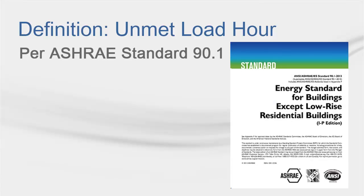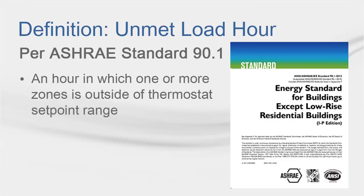Per ASHRAE 90.1, an unmet load hour is an hour in which one or more zones is outside of the thermostat set point range. The total unmet hours of a building are the summation of the number of hours when the heating or cooling set point temperature of a zone is not met by either the HVAC system or plant.